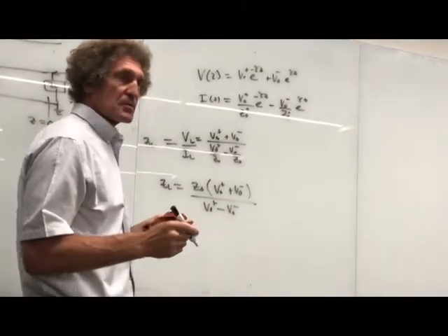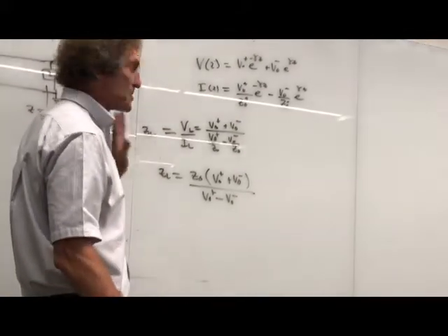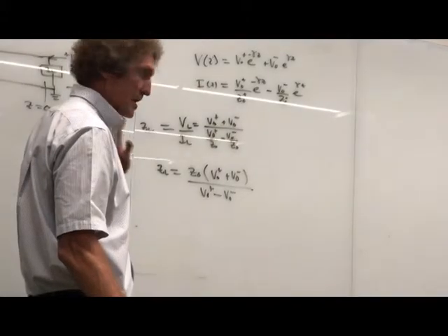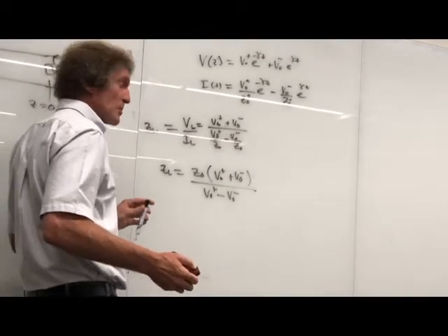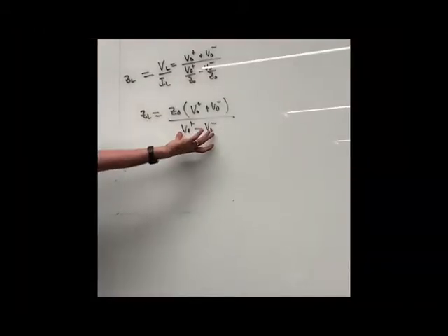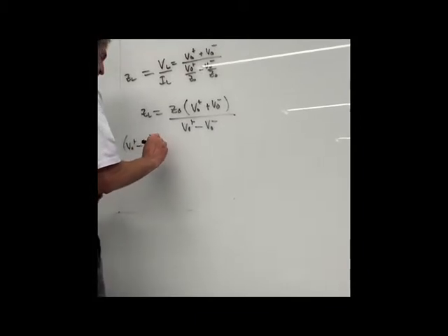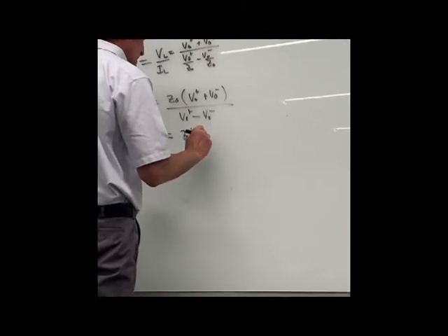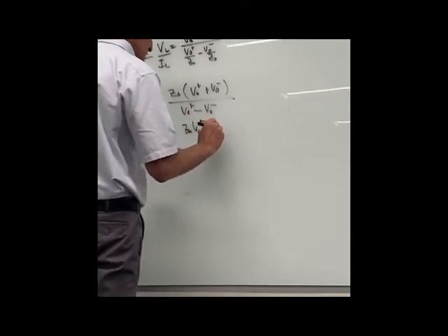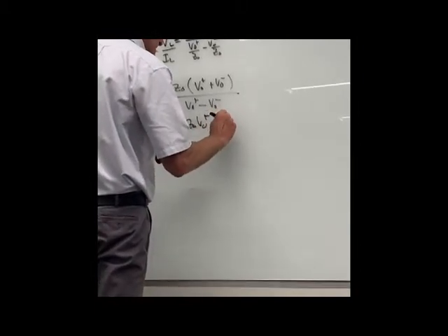And now this is the first thing that you have to realize. There's something called a reflection coefficient, and that's the ratio of V0 minus to V0 plus. I'm going to show you how to get it, but most of you probably see this. If I take this equation and multiply both sides by V0 plus over V0 minus, I get V0 plus minus V0 minus times ZL equal to Z naught times V0 plus plus Z naught times V0 minus.